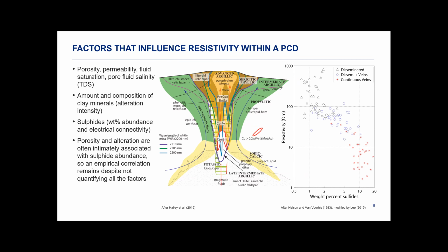They did that to get away from it. But we know that in most surveys we do, the IP anomaly has not died out over the 2 seconds. So you turn the transmitter back on before the anomalies have died out, and it gives you the wrong answer.